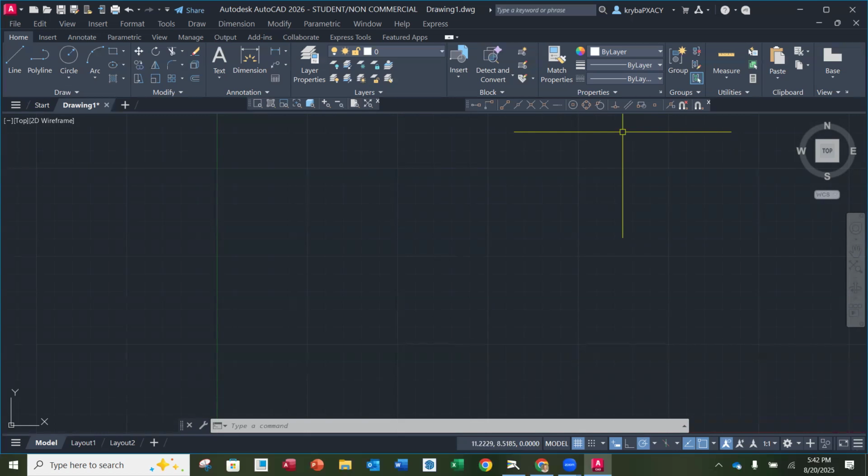Okay. So all we did was zoom to the coordinates that we put in for the drawing limits, they call it, or I like to say it's my piece of paper that I'm drawing on, okay? All this does is get us into the proximity so that you're not zooming super in and out when you're starting a drawing. That's all, okay? All right, so that's drawing limits, and we started with our Zoom Extents for that first one.